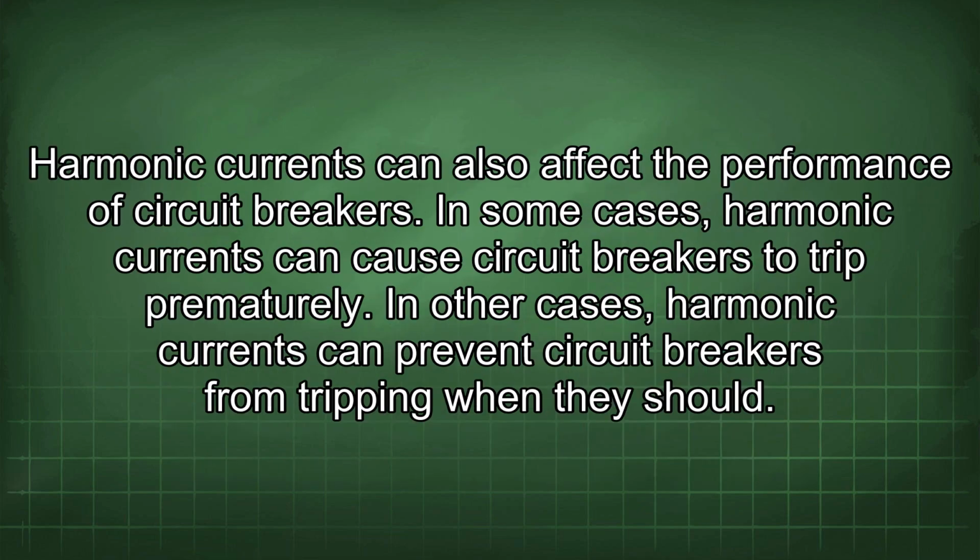Harmonic currents can also affect the performance of circuit breakers. In some cases, harmonic currents can cause circuit breakers to trip prematurely. In other cases, harmonic currents can prevent circuit breakers from tripping when they should.